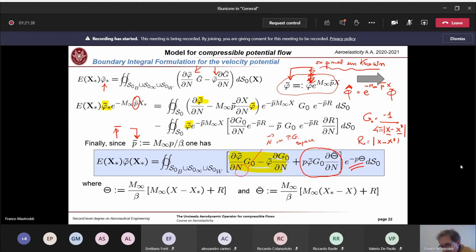As concerning this exponential part here, in Laplace domain, the multiplication of a function depending on Laplace variable to e to the power minus p Laplace variable theta is in time domain a quantity delayed of the quantity theta. So this capital theta is representing a time delay, again a time delay.